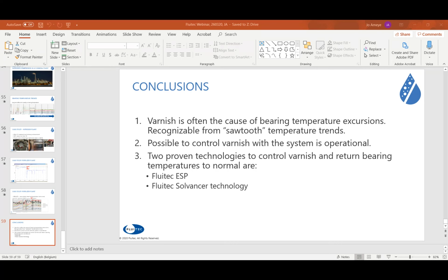So that's why you should not mix oils, because solubility is totally different. Also, the reaction products are different in a group 1 versus a group 2 or group 3 oil. Don't mix them. Make sure you flush, so you don't leave remaining oxidation products when moving to a group 2 or group 3 base oil. I hope it helps to answer your question in a nutshell.